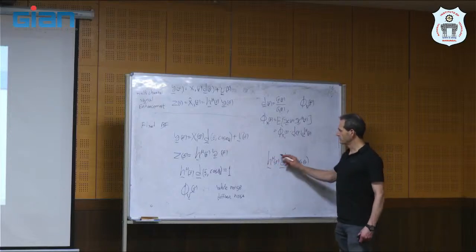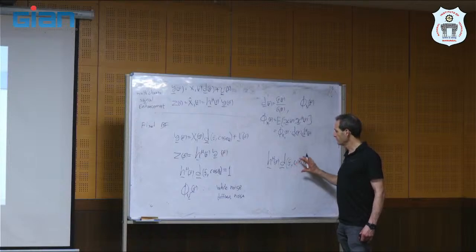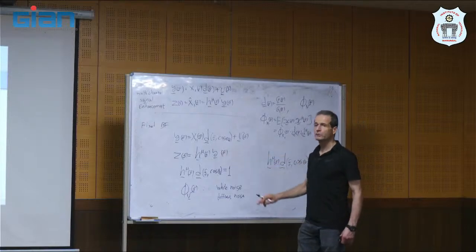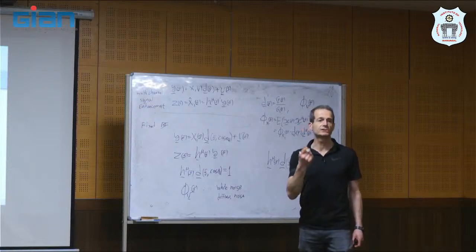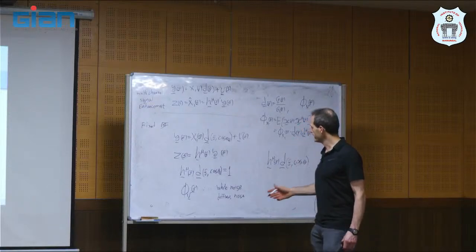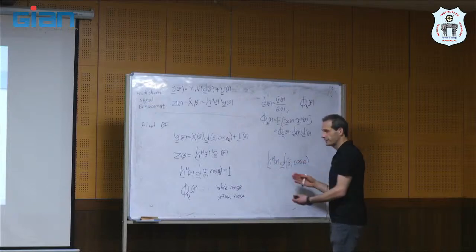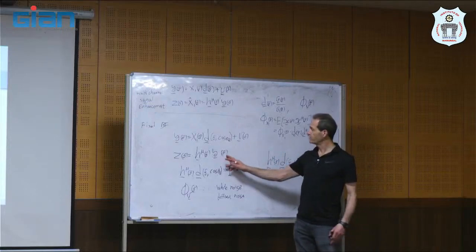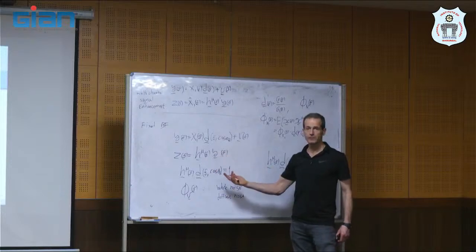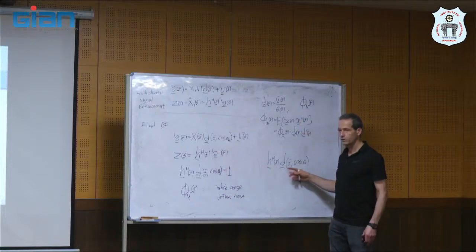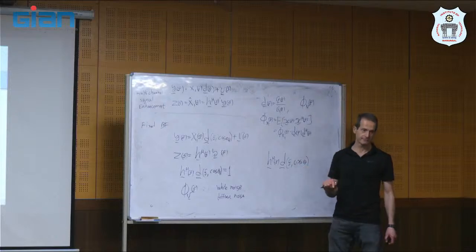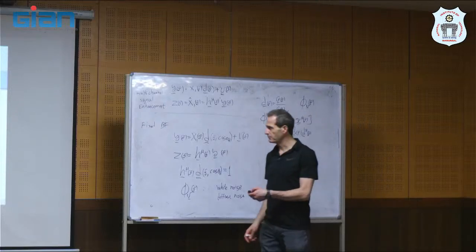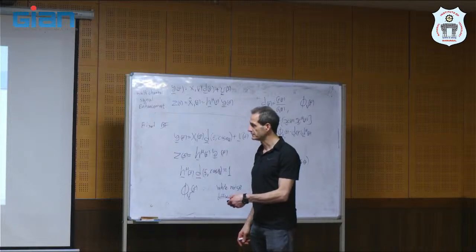This value means how the propagating wave will be measured at the output of the beamformer. What will be its strength? And we can take this magnitude squared, which says what will be the power of the output of the beamformer for a signal that comes from the direction theta. So this is called the beam pattern.